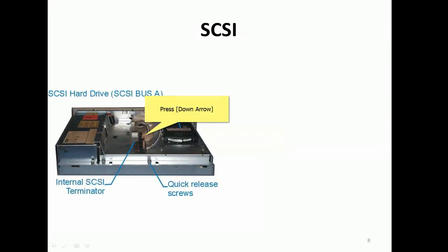That is one example from the industry; I took the diagram from the internet. We have the complete motherboard, and there we have a SCSI bus. Devices are connected: hard disk, and any other device like a printer or scanner. Those connect to the SCSI terminator. The last device, as we said in the previous slide, is a scanner. The last one needs to be terminated. We need to stop the connection there. So there is a bus and several devices connected, and the last device is supposed to be terminated.